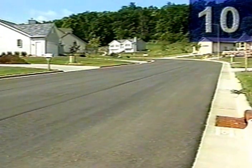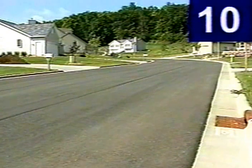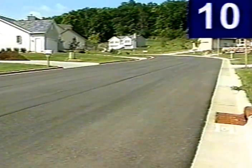With that overview of the rating system, now let's go through in detail. You may look at pages 18 and 19 in the Asphalt PASER Manual if you have that with you, and we'll run through the individual descriptions. A pavement rated 10 is easy to recognize. That's a pavement that's brand new. Here we have an example of a newly constructed urban street. Everything is in great condition, obviously would need no maintenance or repair.